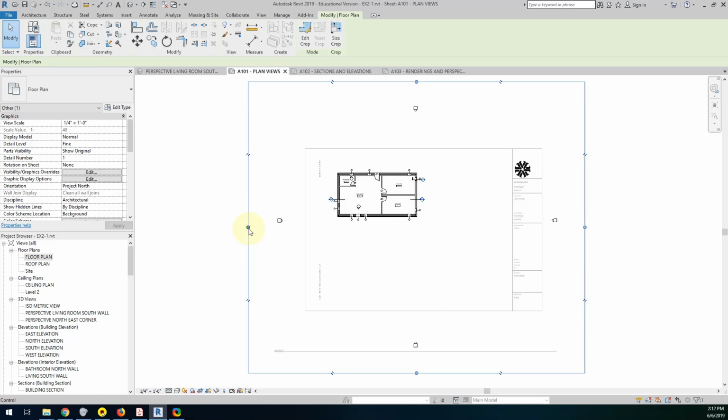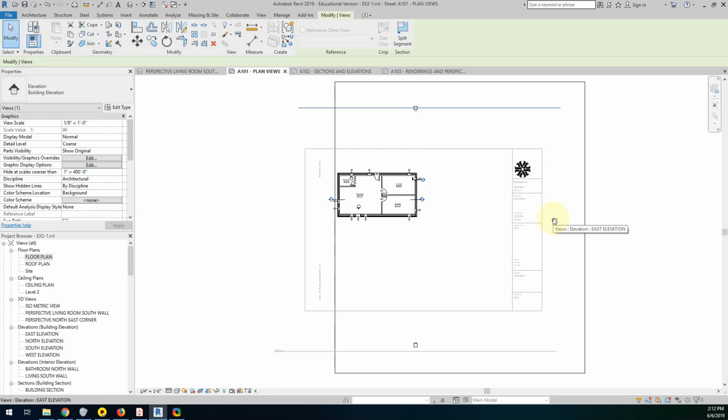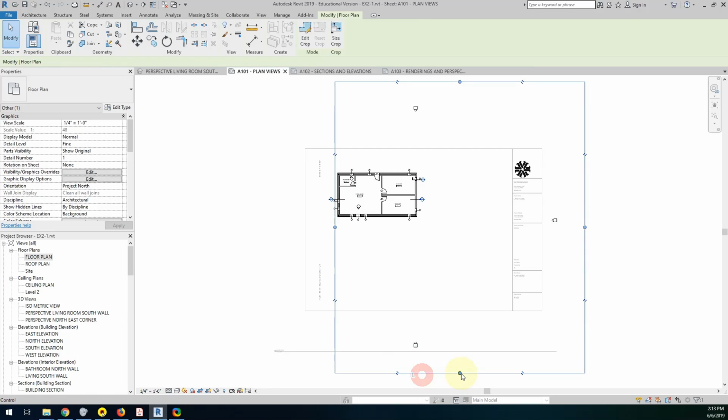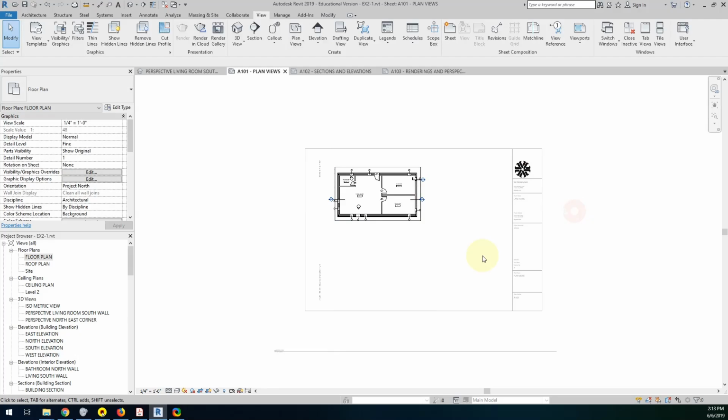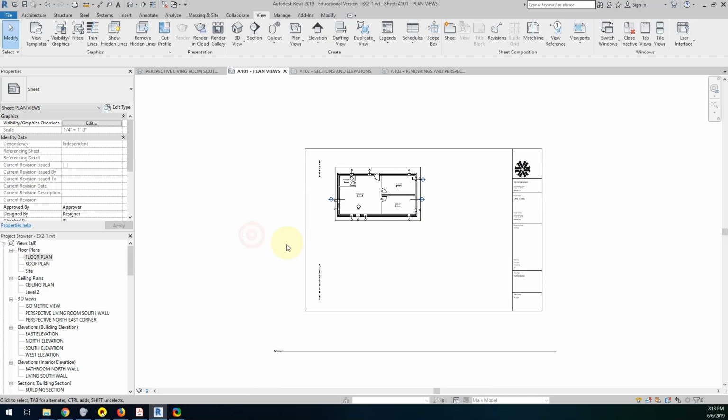So if I click on that box, I can drag it in a little bit closer, or a lot closer, and you'll see the exterior elevation tag has hidden itself. The way those work is wherever these lines are, if that line is not included in the crop box, they will be hidden. So once they go beyond that, it should disappear. Double click to deactivate it.